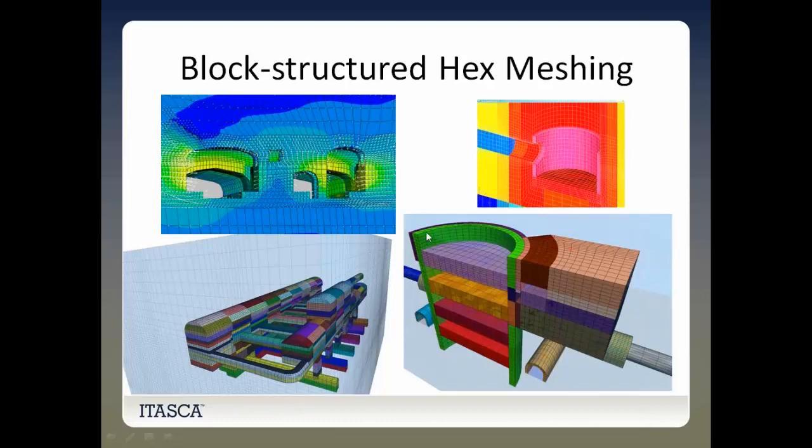In this case, you can see, for example, that we have a liner, some sort of a thin area around this shaft, which has been meshed with 3 layers of zones in some areas, but really meshed with just one zone layer elsewhere. This sort of behavior is an automatic behavior that we could control to some extent, but at the price of an excessive number of zones, because it is not manual, we don't have much control in terms of the trade-off between zone numbers and zone quality.